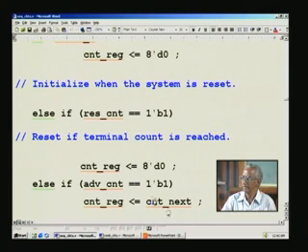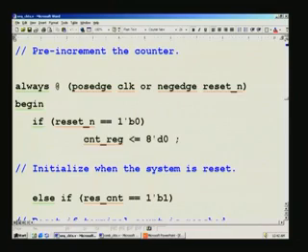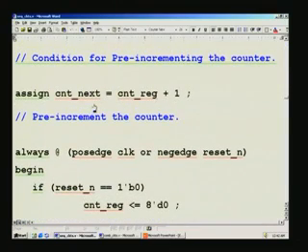You may think that is it not going beyond the time. It won't, because whatever is pre-computed here again depends upon this register only. So it won't keep on incrementing because it is assigned in an assign statement, which is a combinational thing, right. So it depends upon the counter edge. So this will change only with the arrival of the positive edge of the clock. So you can rest assured that this also will change only subsequent to the arrival of the positive edge clock.